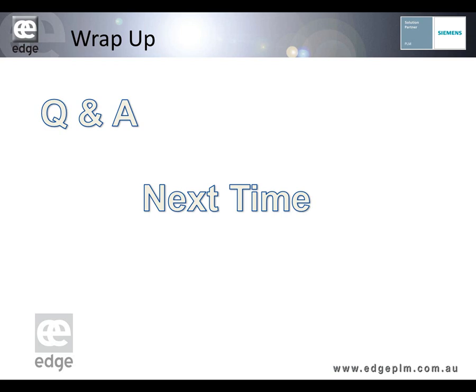Here we go. Can you go back control point pivots? I'm not sure what that means. Can you go back control point pivots? Previous. Yes. In the ordered mode, where you're doing surfaces, all your control points are there all the time. As you saw in that last exercise, you can edit those. You can edit the control points. You can edit the edit points, which are the original creation points. Everything's fully editable. Yes, you can add control points after a curve's created.